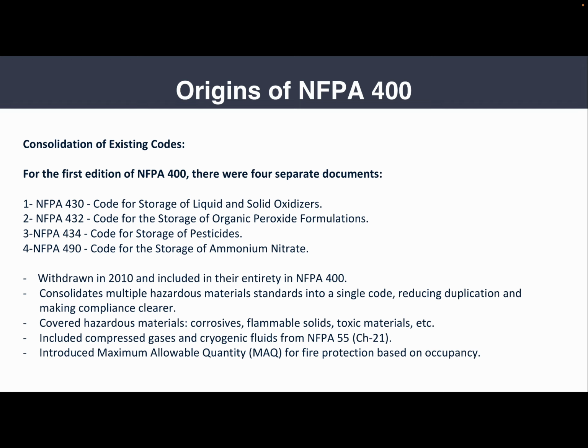In 2010, all four documents were officially withdrawn and merged into one single comprehensive document known as NFPA 400. This new code became the foundation for all hazardous materials because it brought everything together into one place. NFPA 400 also included sections for NFPA 55, which deals with compressed gases and cryogenic fluids, and it also introduced one of the most important concepts, the maximum allowable quantity, or the MAQ.